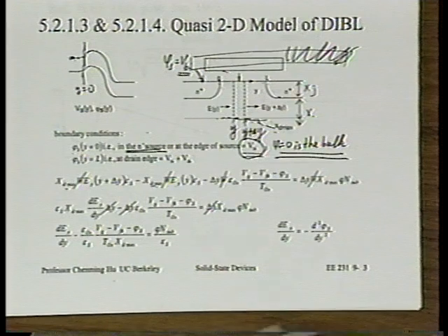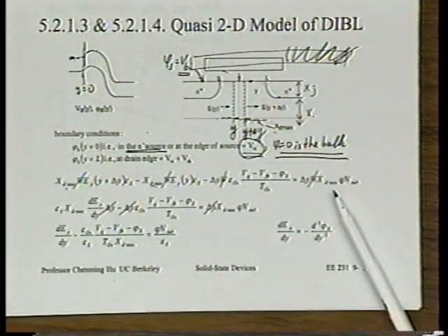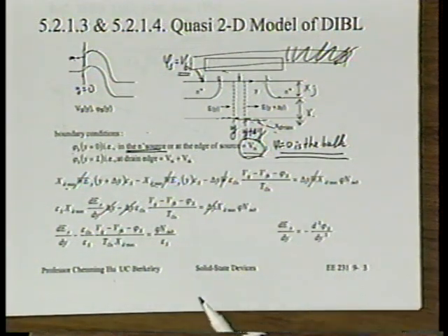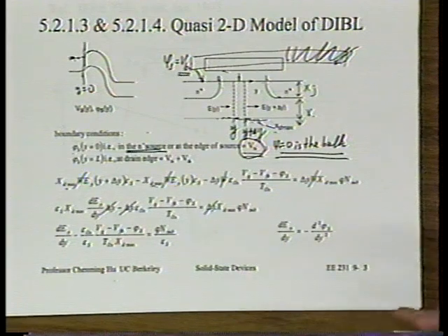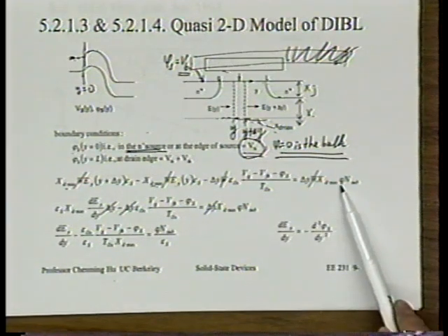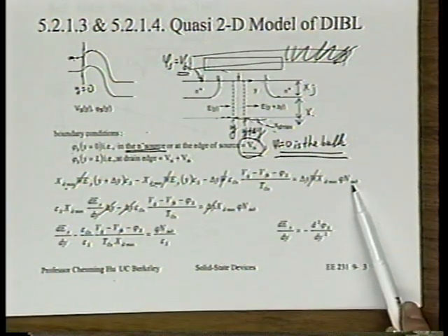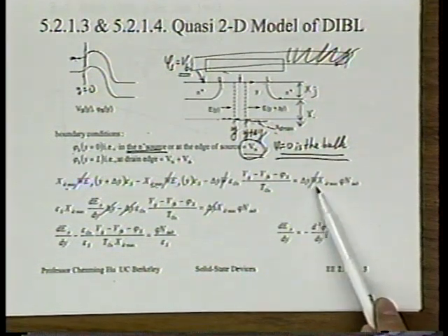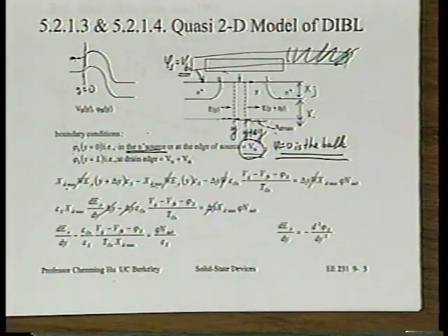Okay? All right. The right-hand side should be all the charge in the Gauss box. Now, remembering that we're looking at a model for VT, so we're looking at the subthreshold region. So there's really no inversion charge, right? It's really just dopant concentration, dopant density. So it should be equal to the volume times q times N sub. And volume is equal to delta Y times W times XD max. Do you agree? That's the volume of the Gauss box. You with me? All right, very good.